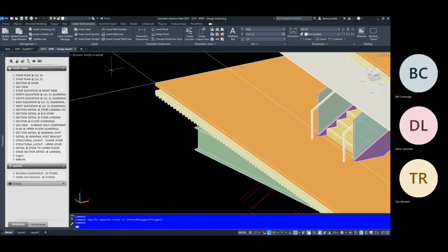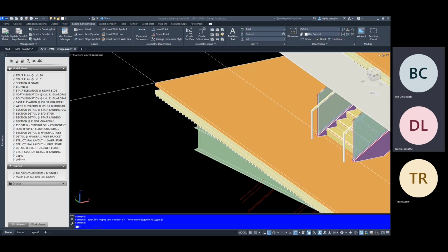Yeah. So I'm not sure about Advanced Steel. I know in AutoCAD there's dimensional constraints, which you can use formulas with. Use the length from this dimension times 2 or whatever divided by 12. You can do basic formulas that way.